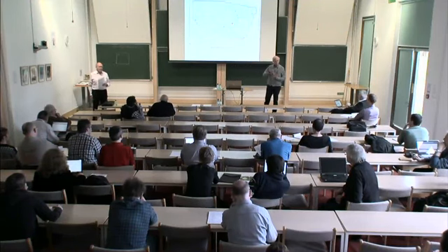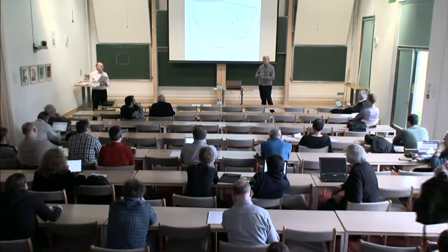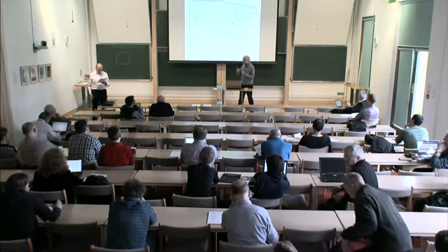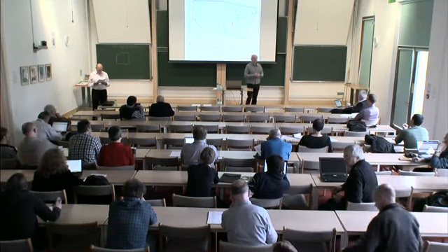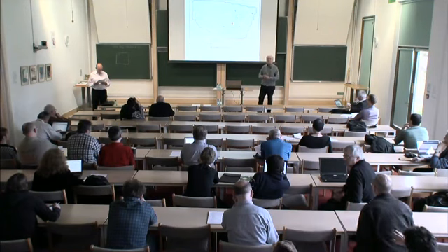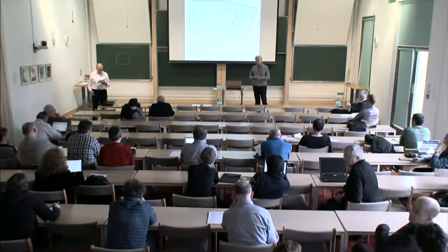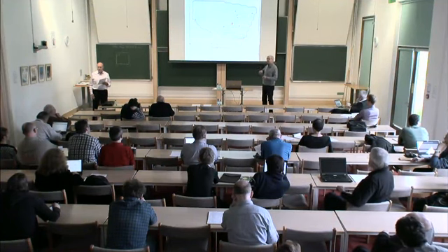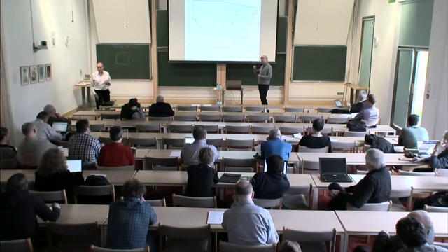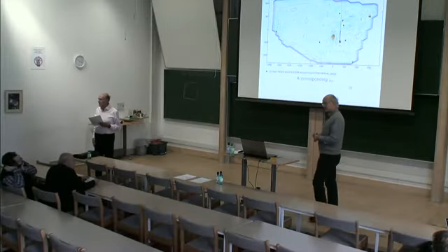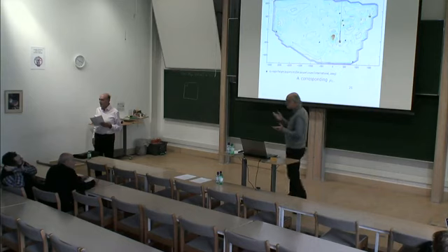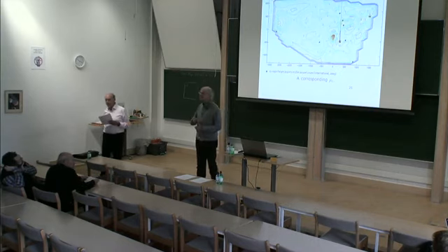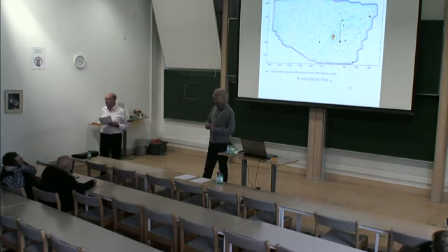But in a flight of medium range, like in the US, most of the cost is the taking off. So this is why this blue curve was concave. This is the main reason. The cruise cost, well, there is some cost, but it is nothing with respect to the taking off.